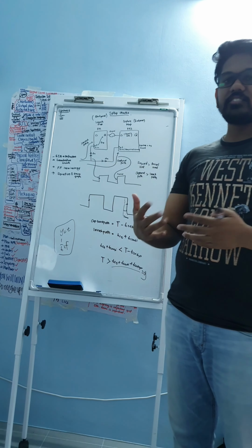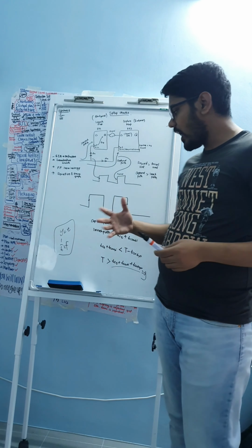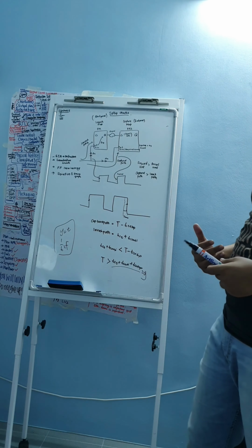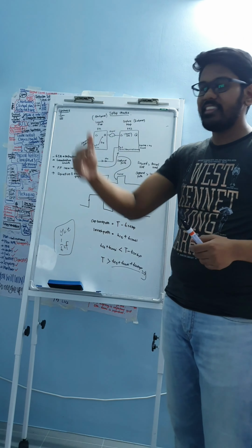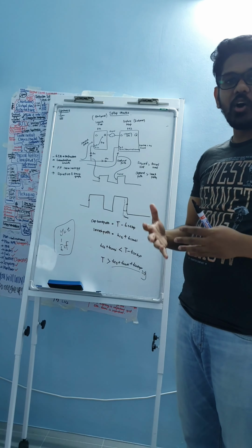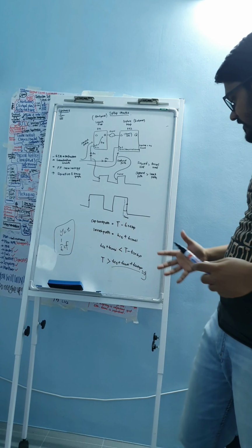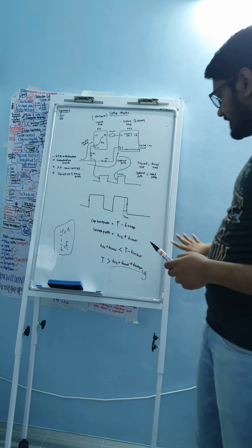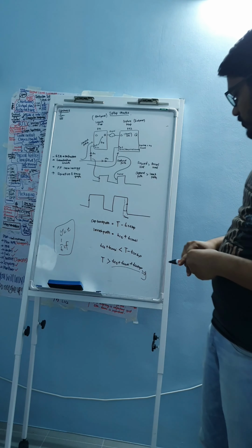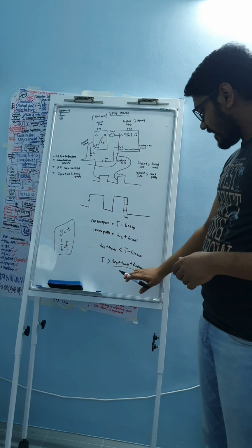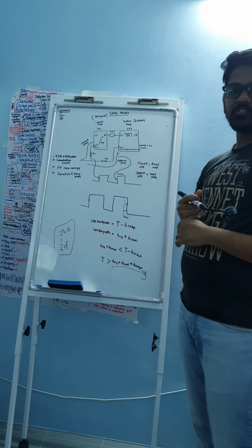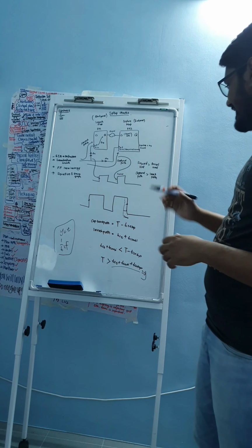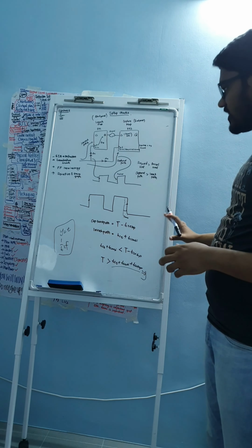Go for a few paths and try to figure out how to set a maximum frequency. From there onwards, you put a threshold that this is the maximum and this is how you're going to converge your design. So over here, it is clearly explained that your data has to arrive earlier before the next clock edge is triggered. So this is the equation for T setup.